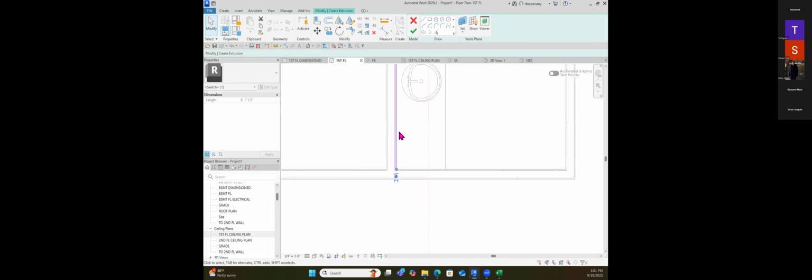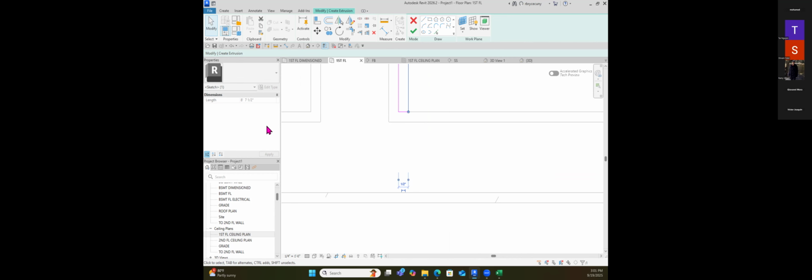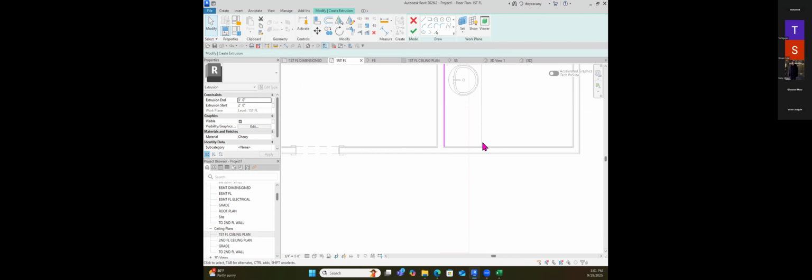See what happened? I picked the object I wanted Revit to move. I changed it dimensionally, and Revit moved that to make this dimension true. Now, what else do we have going on? Well, right now, that mirror goes up 3 feet and stops at 2 feet. So it's the exact same thickness of the countertop.